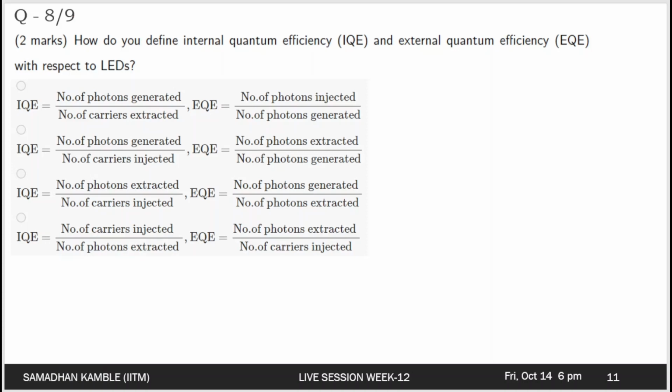For the spontaneous emission, as we see in LEDs, the light can be emitted in any direction, and since the emitted photon energy must be higher than the band gap energy, these emitted photons can be reabsorbed within the semiconductor material. So that is quite a disadvantageous and lossy term for us. The majority of photons will actually be emitted away from the surface and get reabsorbed in the semiconductor material itself. So this is one loss mechanism.